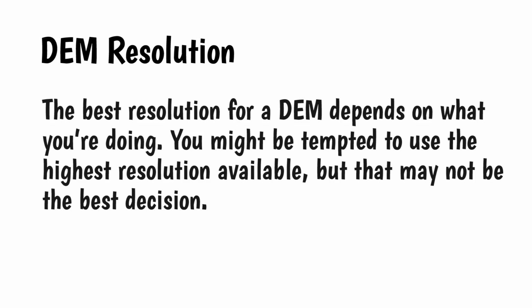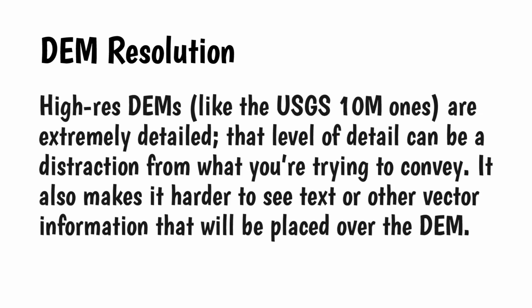DEM resolution. The best resolution for a DEM depends on what you're doing. You might be tempted to use the highest resolution available, but that may not be the best decision. High-res DEM files, like the USGS 10-meter ones, are extremely detailed. That level of detail can be a distraction from what you're trying to convey. It also makes it harder to see text or other vector information that will be placed over the DEM. Here's a scene in Wyoming using several different resolutions.